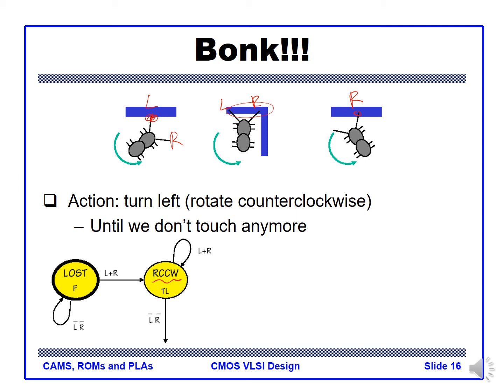First, we will turn left whenever only a single sensor, left or right, is hit. Then we stay in this state and keep turning left. Once none of the contacts, L or R, happen, then we turn left and transition to a new state.